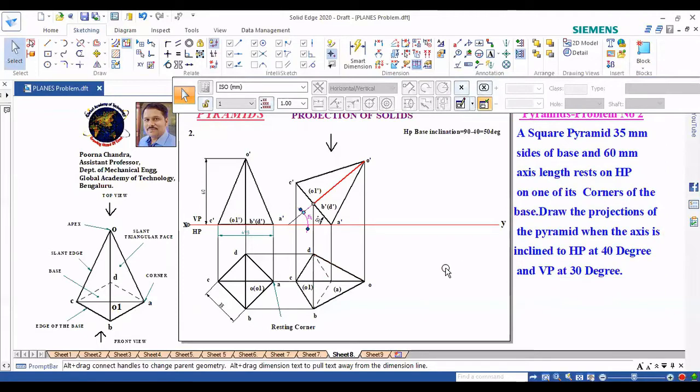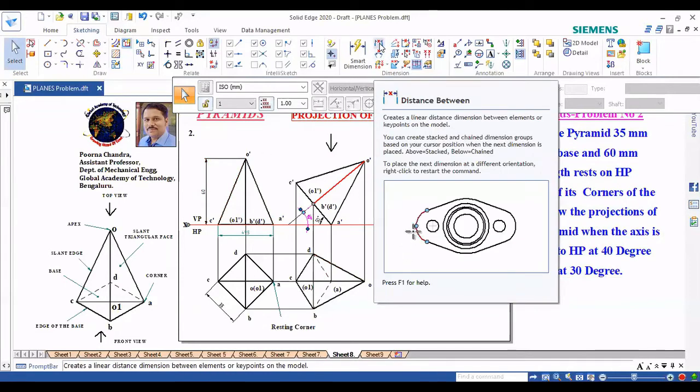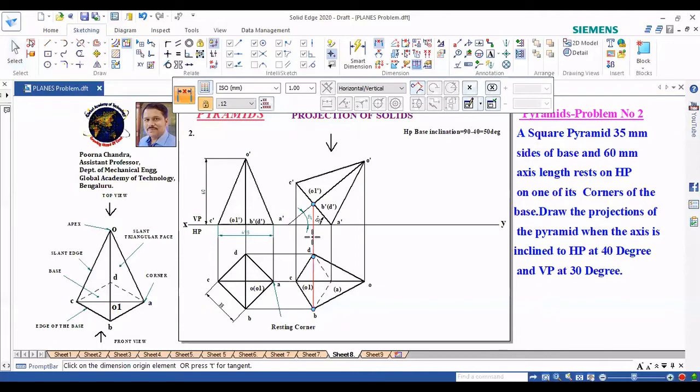So we are supposed to do the beta angle method. In the beta angle method, we need to take two axis dimensions. Here in first position, O1, we have 60 mm, and in second position, we should select the distance between this and this. So measure the O1 length in second position. Here O1 length is 45.96. So that we need to use.